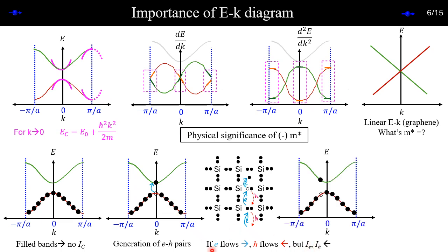Now, if you apply a bias voltage, you break this symmetry. Everything is shifted, this entire distribution of electrons. Suppose we have applied the bias voltage along X. Then this will be displaced along the k axis. Now you can see that the plus k and minus k states will not balance, because it is already asymmetric. That means in that case, you can have current.